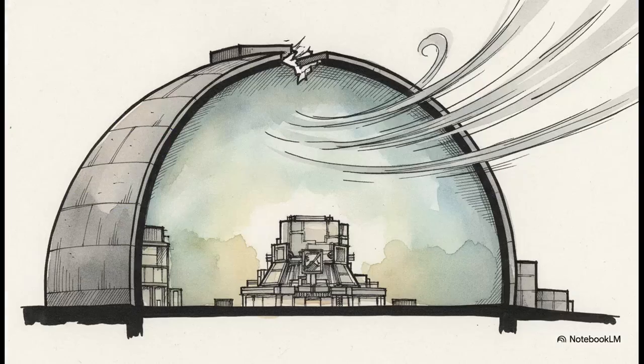It's brilliant. And of course, to ensure maximum safety, this entire complex system is shielded and housed in a containment building that is deliberately maintained at subatmospheric pressure. This is such a smart design choice to prevent outward leaks. Because the pressure inside the building is lower than the outside world, if a breach ever did miraculously occur, the outside air would instinctively rush in, keeping any dangerous material securely trapped inside the facility.